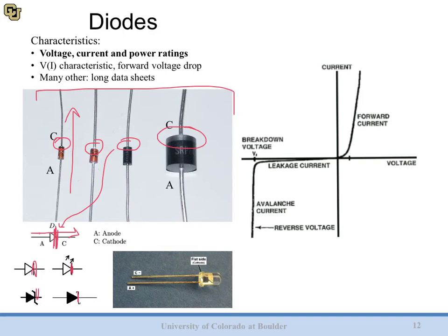If we're using a light emitting diode, which generally look like this, they usually have a slightly flattened edge, which will be the cathode. Additionally, if the leads haven't been cut yet, one of the leads will be slightly shorter than the other. The longer lead is usually the positive terminal. You can also just carefully apply a small voltage to these with some current limit, and if it lights up, it's in the right way. You get the point.